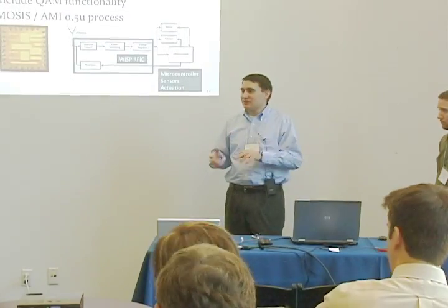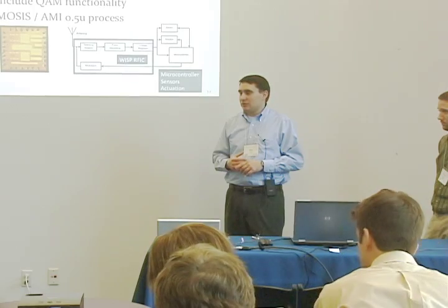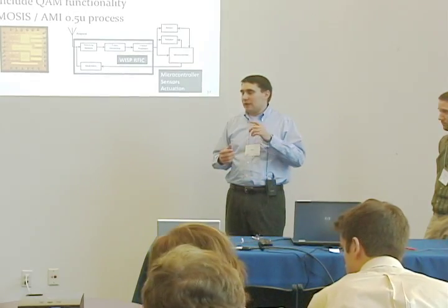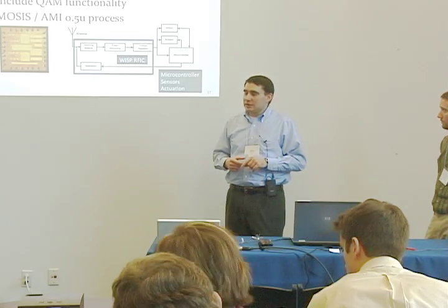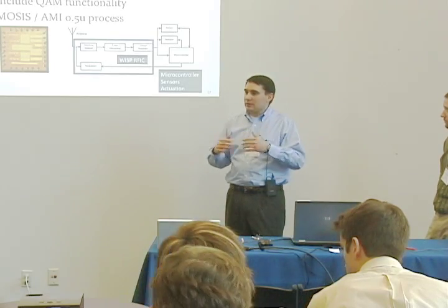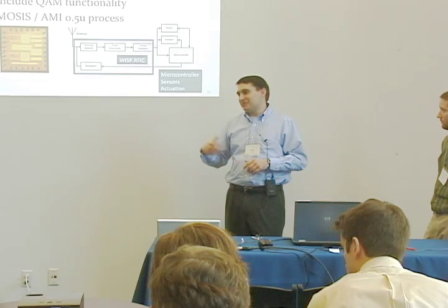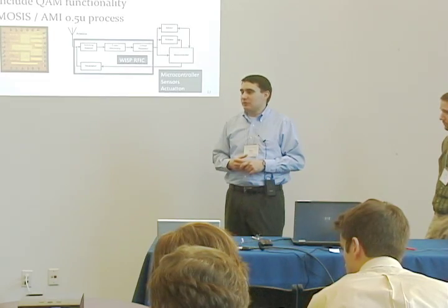Do you know whether the Schottkys or the diode-connected transistors perform better? According to the simulation, they perform better in different regimes. The diode-connected FETs perform better under a different set of matching conditions than the Schottkys do. In general, the Schottkys have a much higher efficiency at low input power, but they have a relatively high equivalent series resistance, so they supply less current at high input powers. So there is a trade-off there.